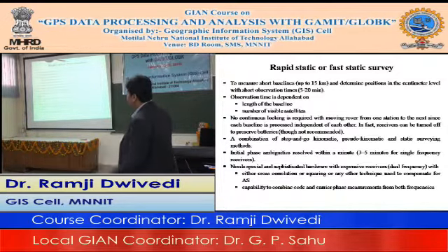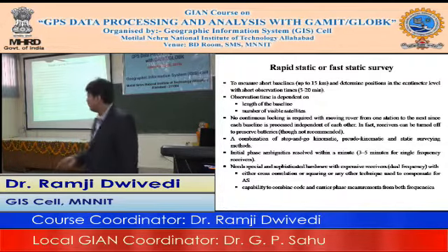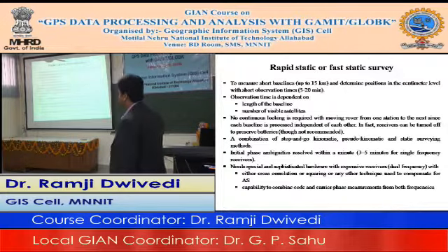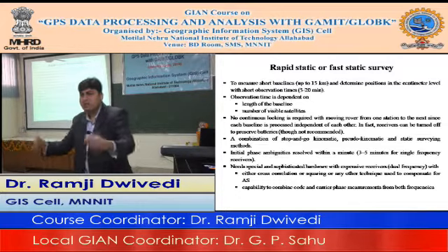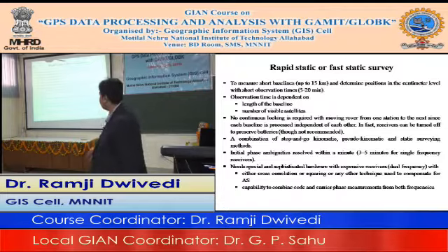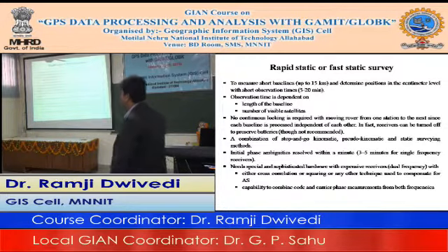So yes, this is a slight deviation from the pseudo kinematic. We could say that no continuous lock is required with the moving rover from one station to the next, since the baseline is processed independently. So we are occupying the station and moving, and the need for lock is not required in this case. It is a combination of stop and go kinematic, pseudo kinematic and static surveying methods, but the quality of the receiver should be of higher grade.